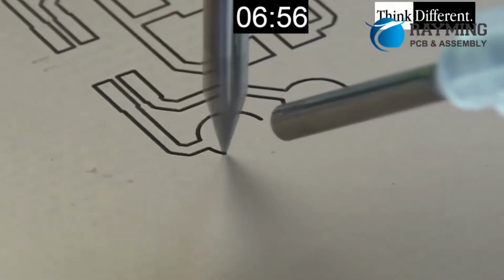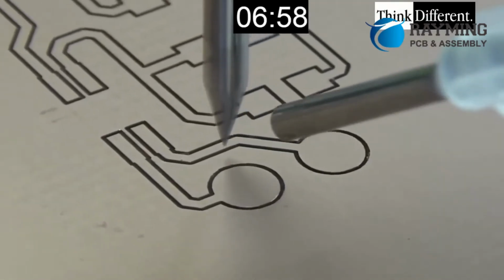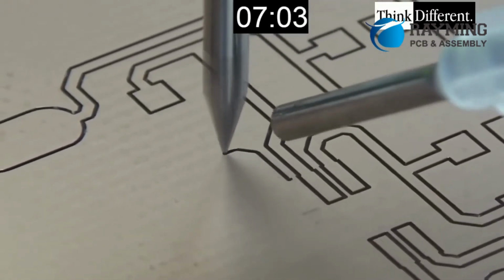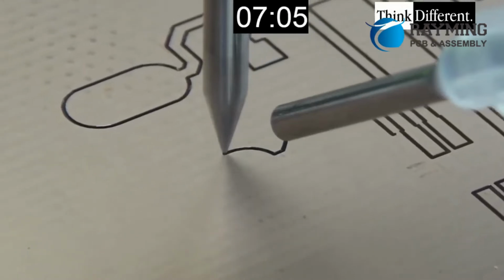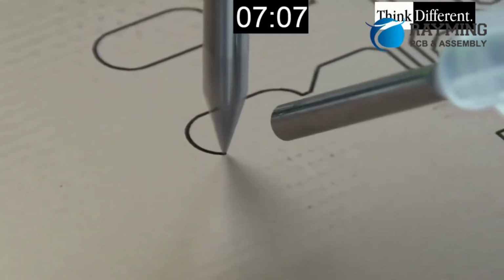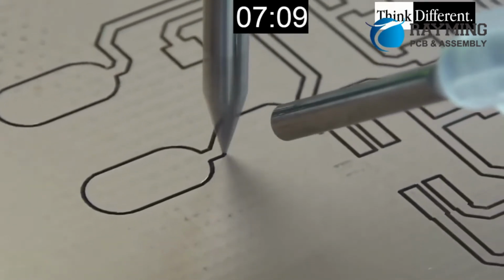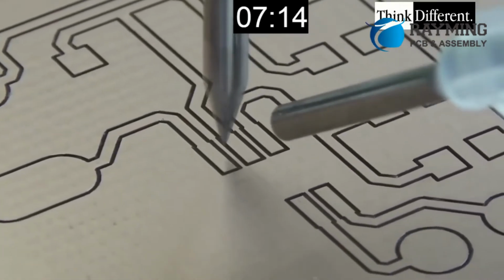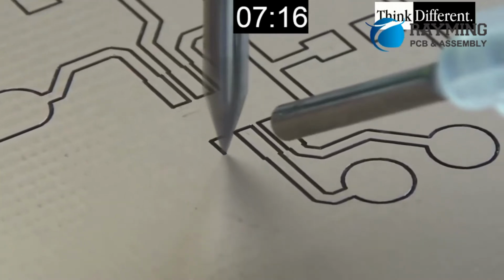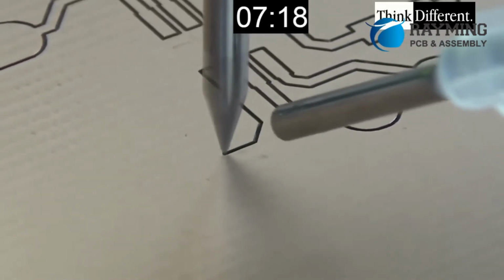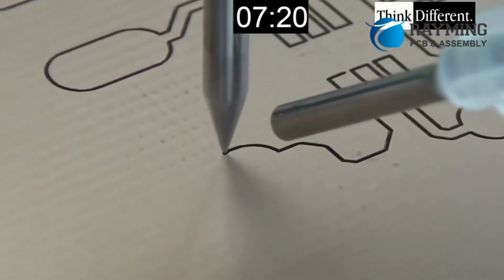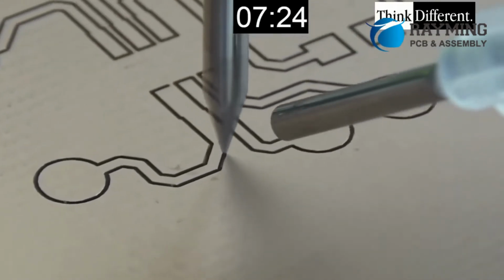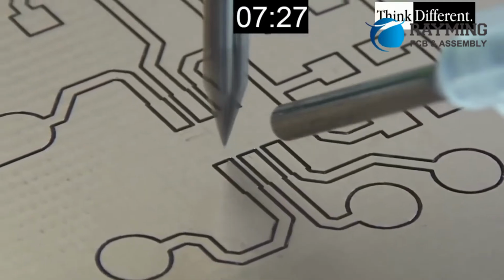PCB manufacturing requires the use of vias in order to make electrical connections. These holes are drilled with certain tolerances, and you may also manufacture them off location. Therefore, allowances for drill position errors are necessary before manufacturing. Without proper vias, manufacturing yield is reduced. In addition, regular through-hole vias must be plated. Various processing steps are needed to ensure that the through-holes are plated properly. The result is a layer of thin orange and gray materials that makes the electrical connection.